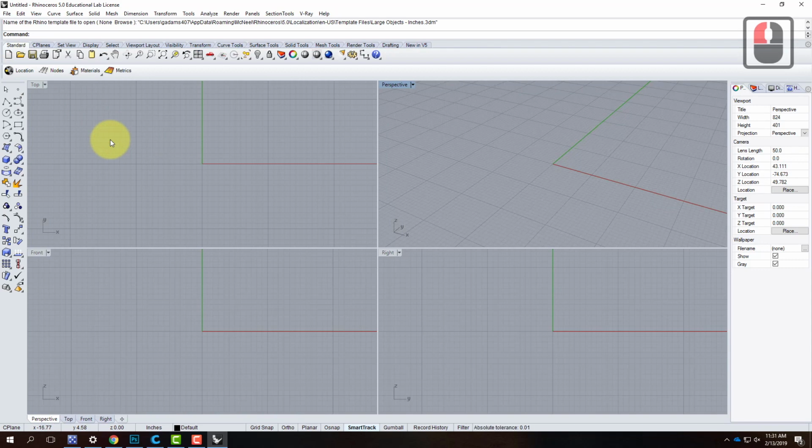So in part 1, I'm asking you to draw the shape to the right of the little handout here. And what that shape is, it's 2 arcs that are 2-inch by 2-inch arcs, so it's a 2-inch radius. And then it is a 13-inch line and then another 2-inch radius arc. And when we start to draw arcs, we have a bunch of different options. And so you have to think about which of the options make sense. I'll start with this option first.